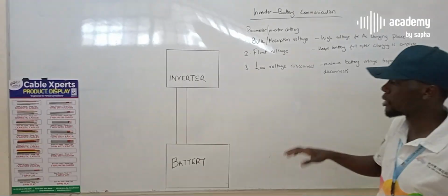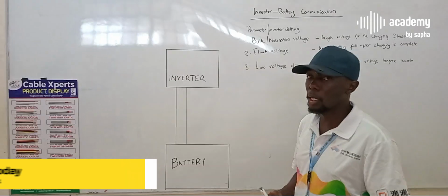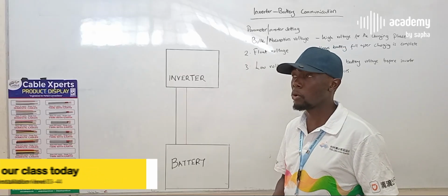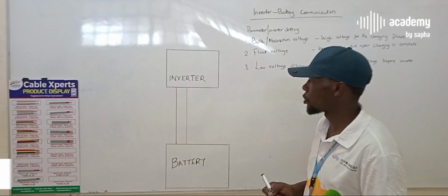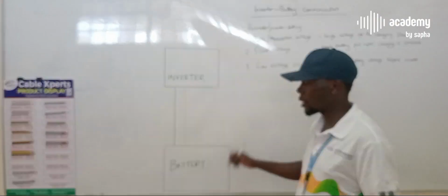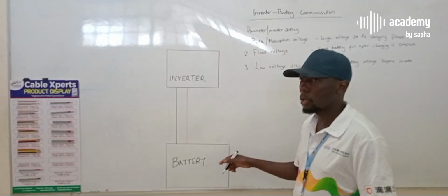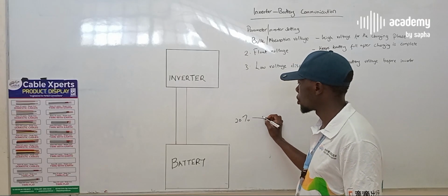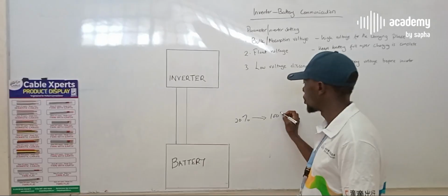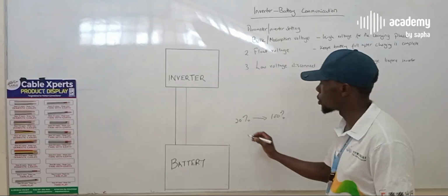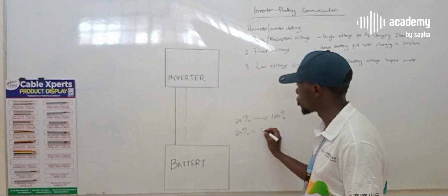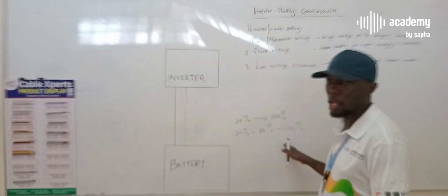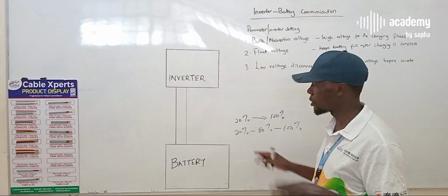And I had explained that the charging phase might come pre-programmed, or you can adjust the program if the inverter allows you. So this means, for example, you want to lift the battery, let's say in a charging cycle, early one morning, the battery is at 20%, and you want to lift it all the way to 100%. So we've got stages. It will come from 20% probably to 80%, then to 100%. This is not a fixed design. These designs do vary. This is just an example.